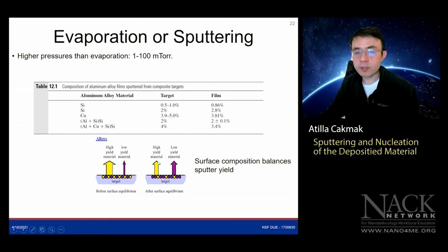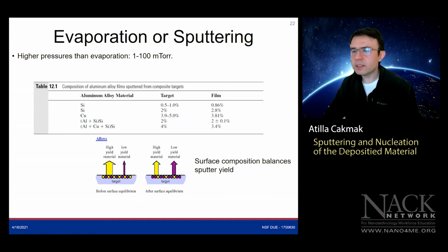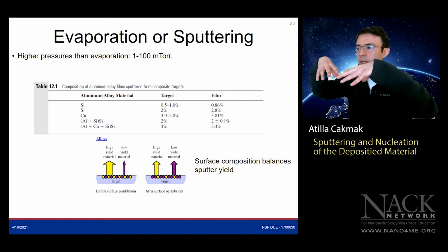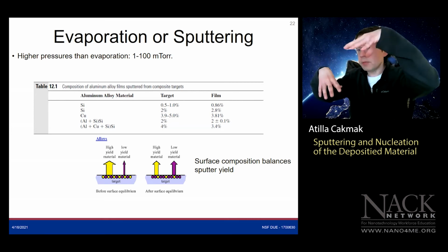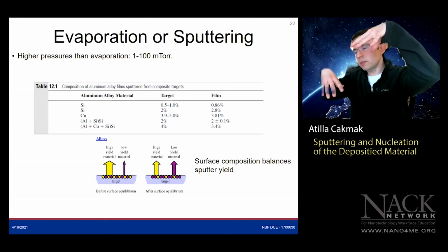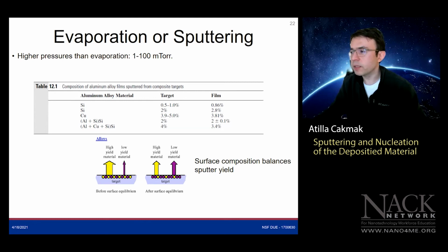So, okay, a couple of the intelligent students will ask, that doesn't sound reasonable. You just talked about the sputtering yield, and now I have two elements forming the alloy, and their sputtering yield will be different. Now, not their melting temperature, but their sputtering yield will be different. So there's also a segregation, not because of the temperature, but because of the sputtering yield, they will say. And I will say, wonderful point.